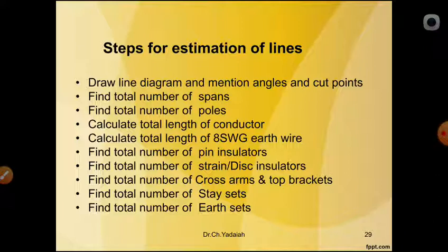These are the main things you are going to estimate: how much of the material is required, and what is the approximate cost for erection of this line. Now prepare a schedule. Whatever you have calculated, prepare it on paper in a table, that is known as the schedule. The schedule will give the overall idea of how much material is required, what its specifications are, and how many numbers of these materials are required.